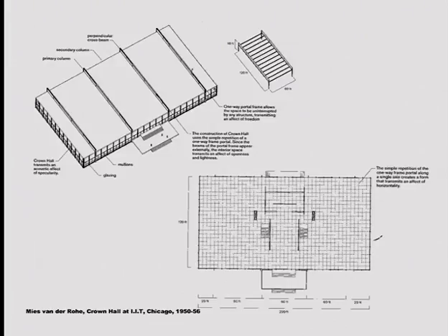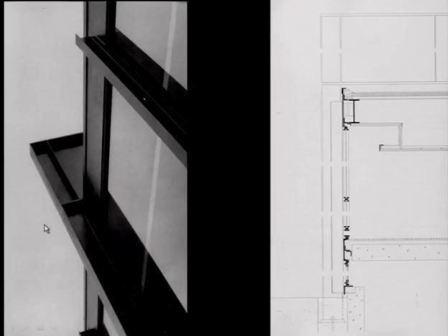So that's the idea of repetition of standard elements, because between this portal frame and the second one, we get a bay. So this is the architectural bay we replicate throughout the process, like in the old Gothic churches. Again, no bolts, these are all rigid connections. You see very clean and nice welds. So everything clean and nice.